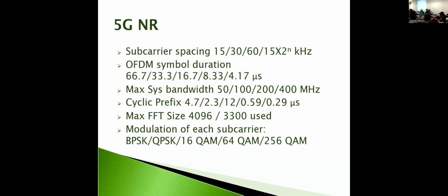The point being that those modulations are the most robust to errors, right? Think way back, before the midterm, when we were calculating the error probability of binary antipodal modulation, which is another word for BPSK, and we found that it had the best error immunity.